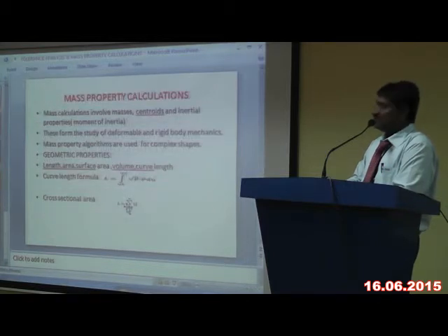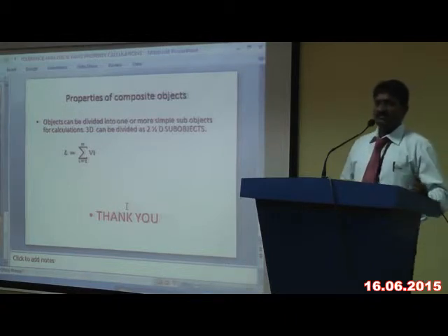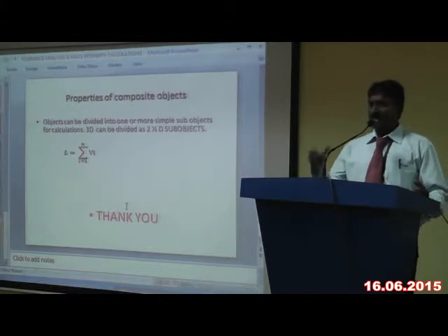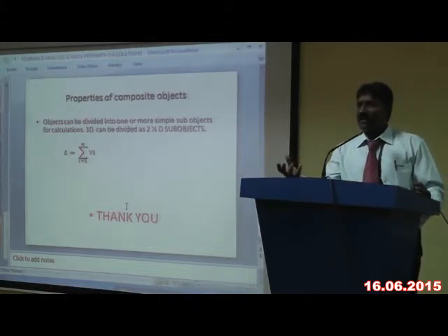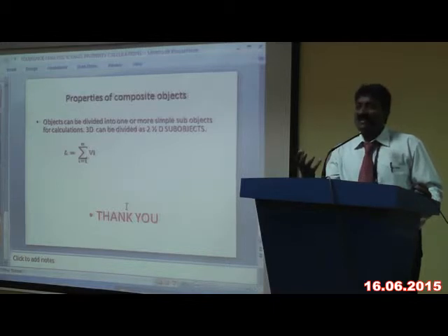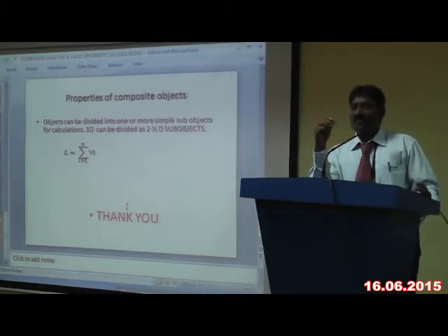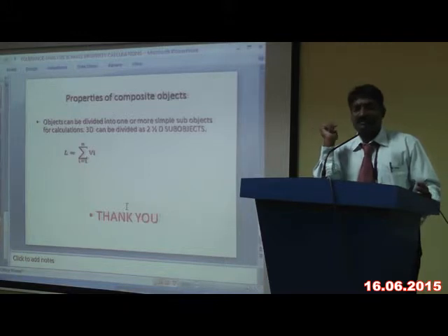And mass property calculations, you know. Ask them to take one very simple component from a bike or from a car. Ask them to find out what the mass of it is and how it can be reduced. What other alternate materials can they use so that the mass is reduced, but the functionality should be the same, or better. The functional aspects should be better than the previous one, or even if it is equal, no problem, right? So like this you can give some work for your students. It will be really nice, right?